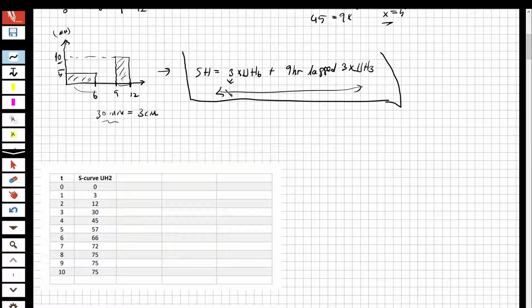First, I'm going to start with the unit hydrograph for 3, okay? If it is 3, I need the unit hydrograph 3, okay? Listen here carefully. I need to lag for 3 hours, okay? If it asks unit hydrograph for 3, I need to lag for 3 hours. So 1, 2, and 3, okay? I'm going to start with the fourth one.